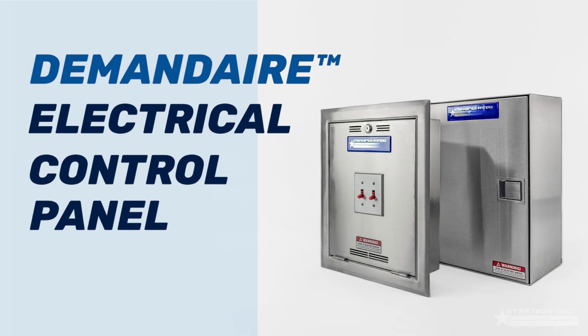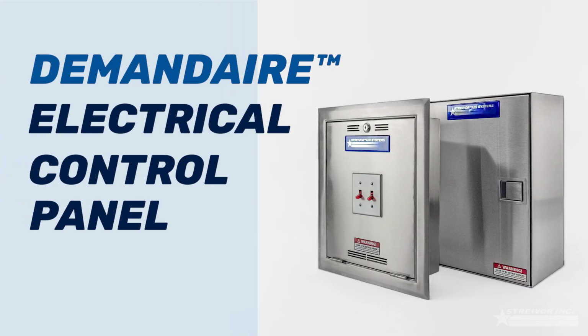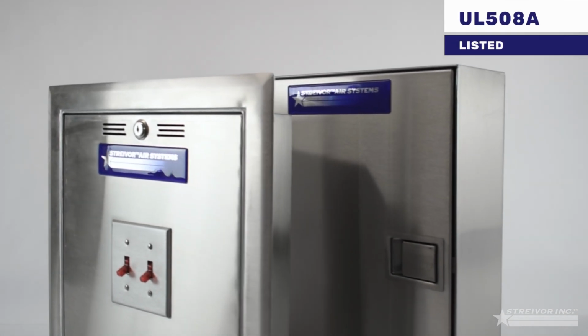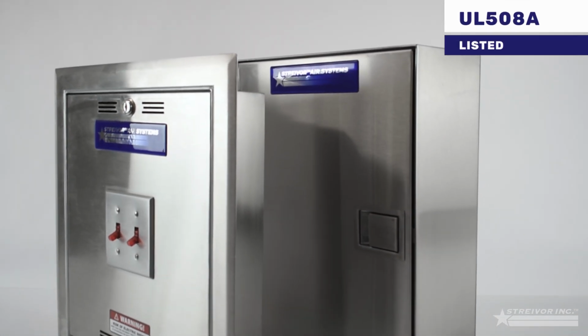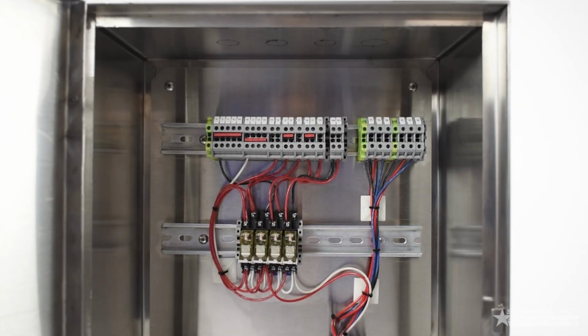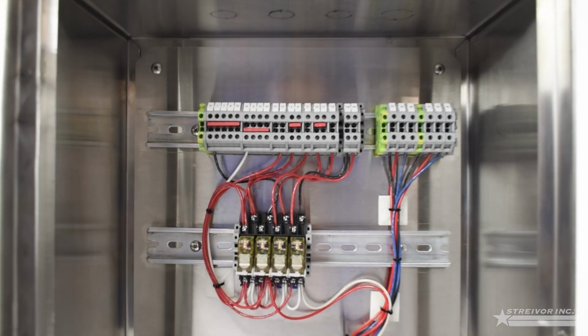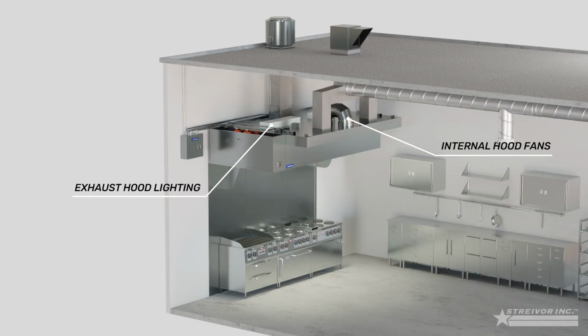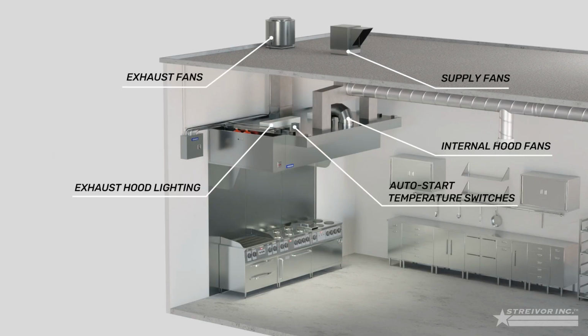This video will consist of Streivor's DemandAire Electrical Control Panel, ECP. The ECP is a UL 508A listed hood system control panel for commercial kitchen ventilation hoods. The ECP houses electrical terminals to provide electrical connections to the hood system accessories, such as the exhaust hood's lighting, internal hood fans, if included, auto start temperature switches, the exhaust and supply fans, and the hood's fire suppression system.